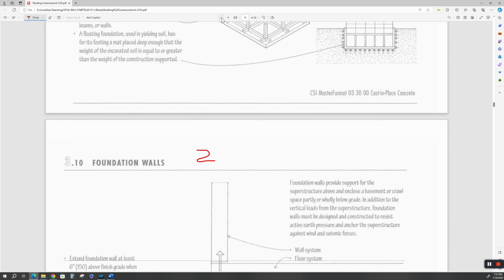All right. Plus, these things have to be constructed properly. You've got to watch the mortar. These things have to be reinforced, and the cells have to be filled with concrete. Okay. I'm not a big fan of these. These, yes. Yes, this costs more money, but it's more permanent. And if done properly, it will outlast these.